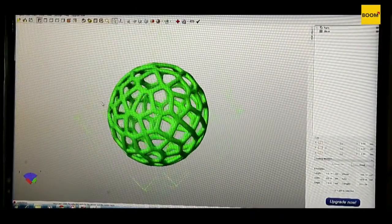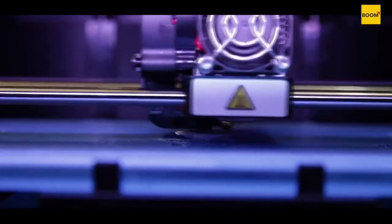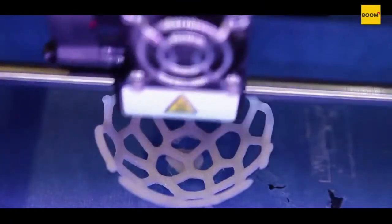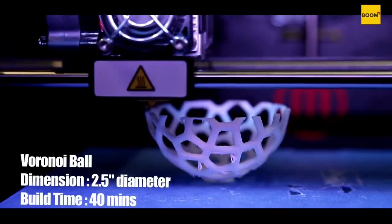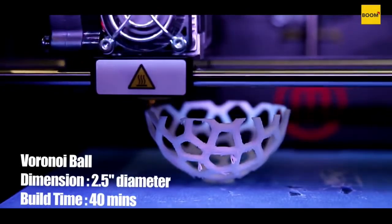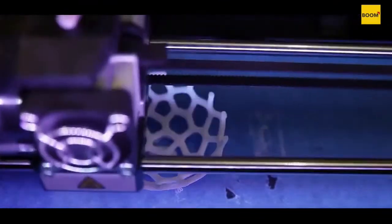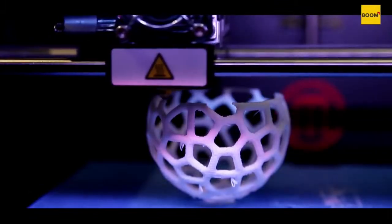If you have an object that's quite high in its vertical dimension, this means that the printer will have to make a large number of horizontal layers, each one above the other, while making your print. This will increase the print time. Typically, print time varies from about 15 minutes to 10 hours. The most common materials for 3D printing are plastics such as PLA, ABS, and nylon. But you also get printing technology these days that can make objects from ceramic or metal powders and convert them into actual metal or ceramic objects.